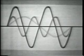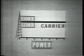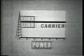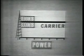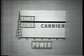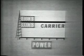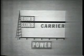But back to the composite waveform. Let's look at it in a little different way. We'll begin to see some undesirable things about the conventional AM signal. After the sidebands are generated, the carrier is not required for transmission of the sidebands. Now, since the carrier is constant in amplitude and in frequency, it contains absolutely no information at all. So why transmit it? Yet 2/3 of the total power is wasted in transmitting the carrier. Thus, the sidebands are being deprived of power which might increase the range of transmission.